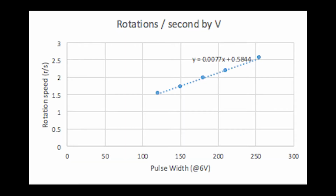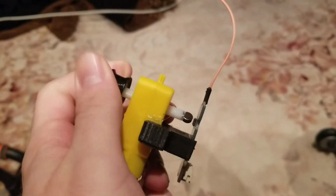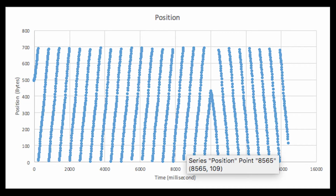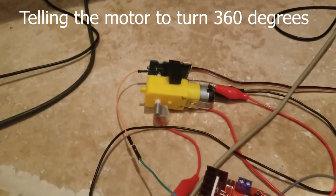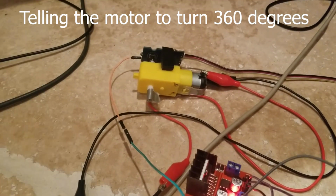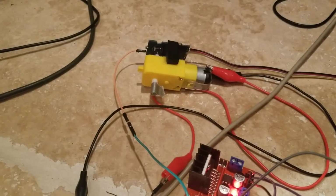Using this data, I was able to model the output of the motor. Feedback comes from these little Hall effect sensors, and when the magnet changes its angle, this wire here outputs an analog voltage that is dependent on the angle of the magnet. Turning the output of this sensor into a positional output was extremely difficult, especially because the signal is very noisy. Eventually, I was able to tune the motor's response with a high degree of accuracy. We got the speed up to 99% of the desired output, and positional accuracy was within 10%, under no load.